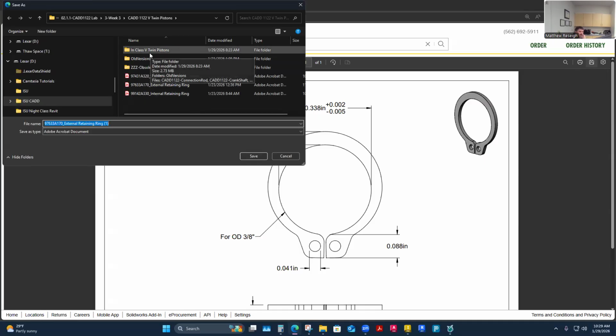This is how I know how to modify my model to accept this fastener. I need to know these dimensions. The way this works is you cut a slot in your shaft that'll accept this little snap loop. So I actually have to make a groove cut.